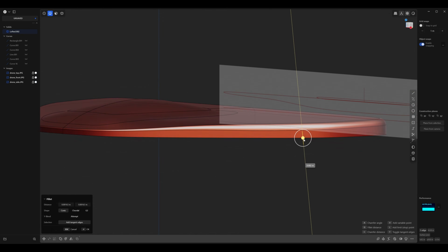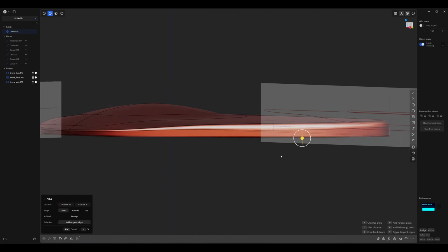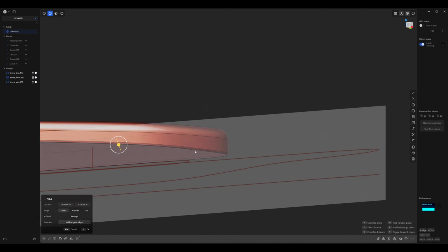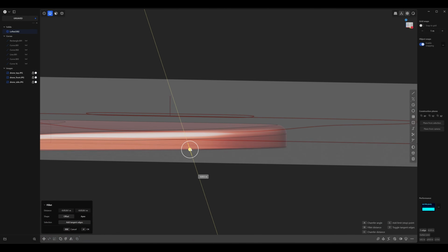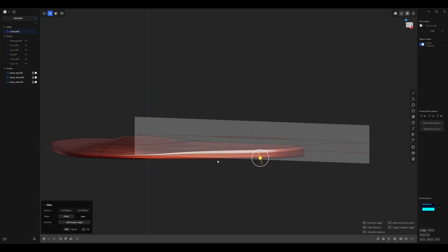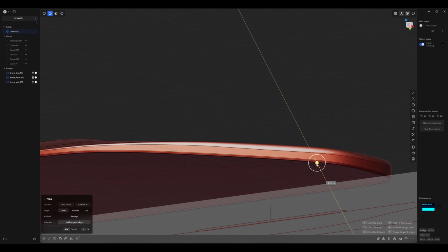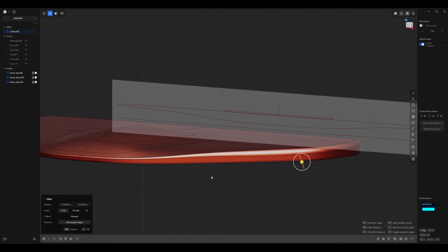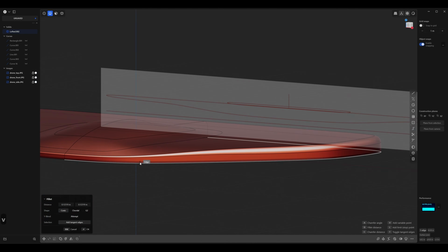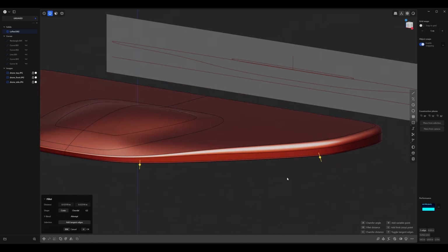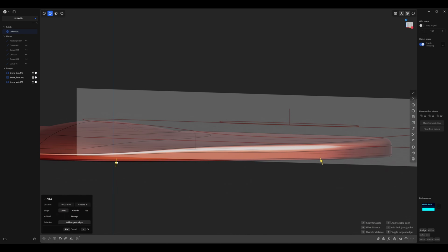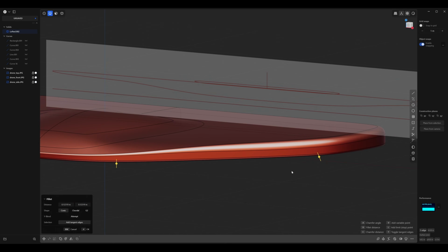And remember, you need to actually hover to create an initial fillet, which is what I didn't do here. Looks like a chamfer, so let's go in the opposite direction. Press V, select once here and once near the back. And now we have the same two options. So let's keep that size over there, and let's widen this one out a little bit.